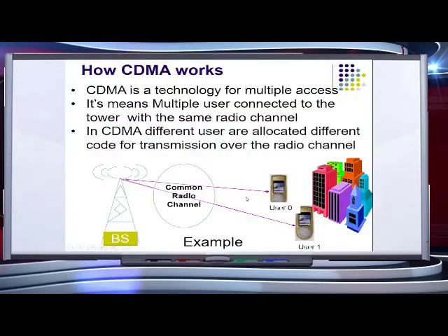Now let's understand CDMA. CDMA is short for Code Division Multiple Access, a digital cellular technology that uses spread spectrum technique, unlike competing systems such as GSM that use TDMA. CDMA does not assign a specific frequency to each user. Instead, every channel uses the full available spectrum. Individual conversations are encoded with a pseudo random digital sequence.